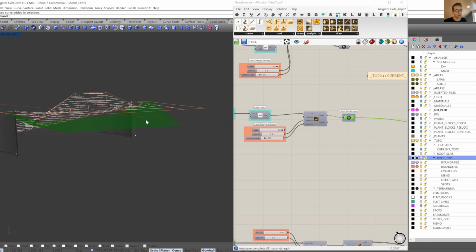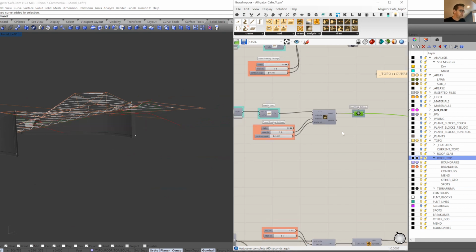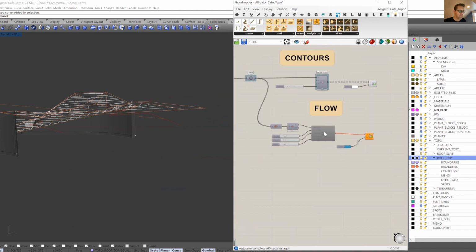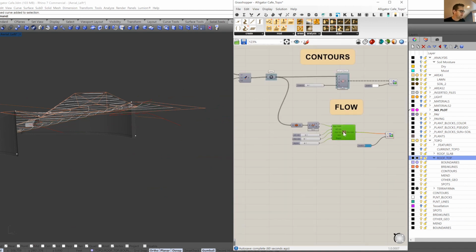Very often the waterproofing layer is below all of the foam, below all of the soil. And a civil engineer might even say that that is the level you need to think about for water. We do, of course, look at water as well, but we are looking at it a little bit more superficially on the top.